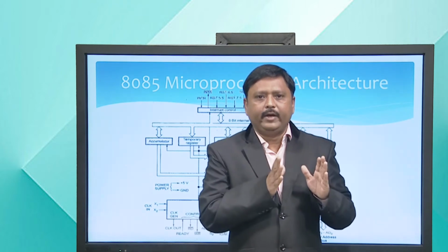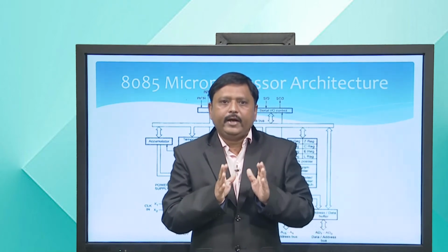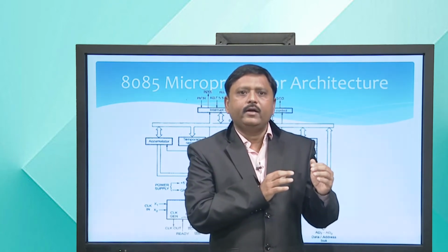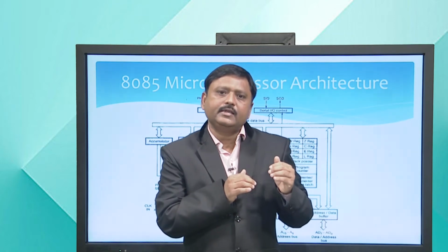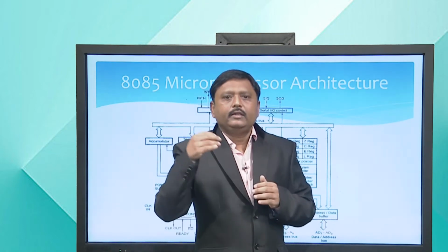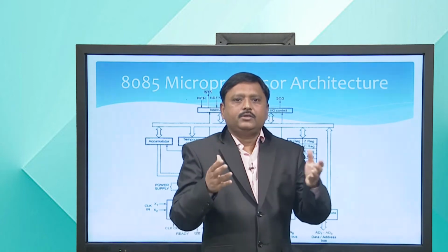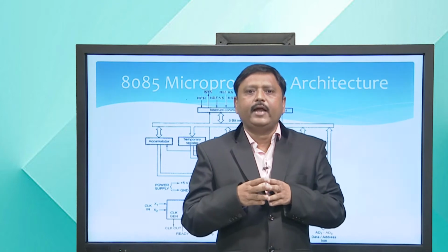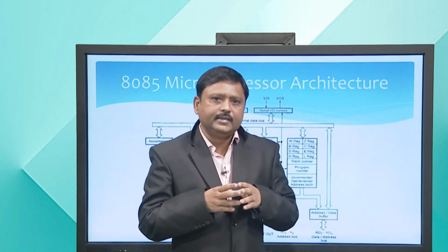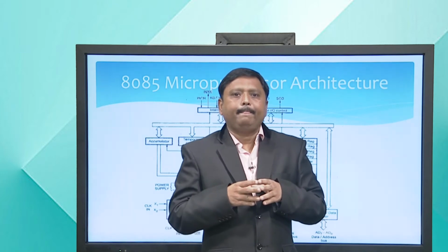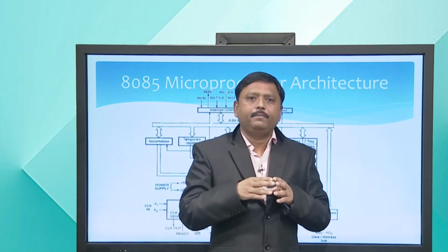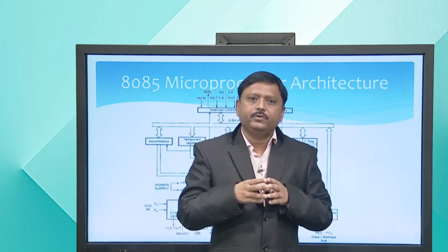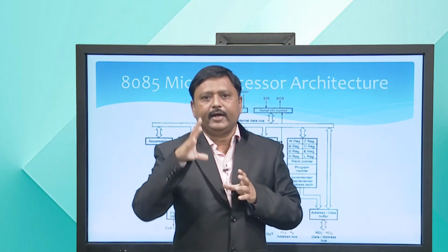It consists of memory, where program, data and stack memories occupy the same memory space, and the total addressable memory size is 64 kilobytes. The program can be located anywhere in the memory. Jump, branch and call instructions use 16-bit addresses, and these instructions can jump anywhere within 64 kilobytes. All jump and branch instructions use absolute addressing, that means static addressing.